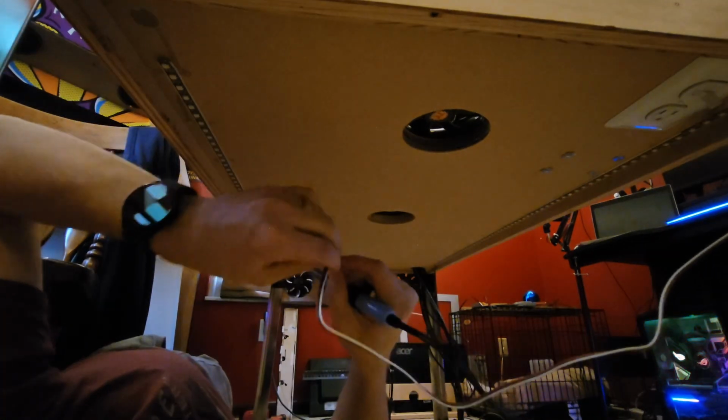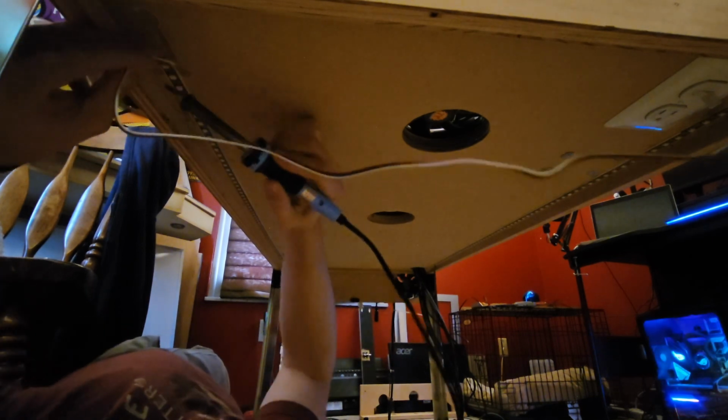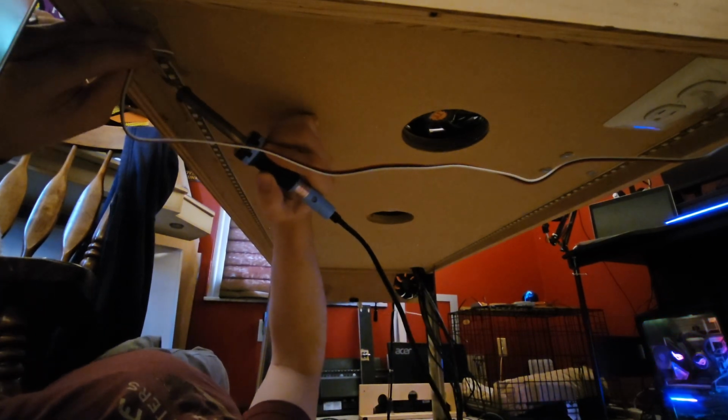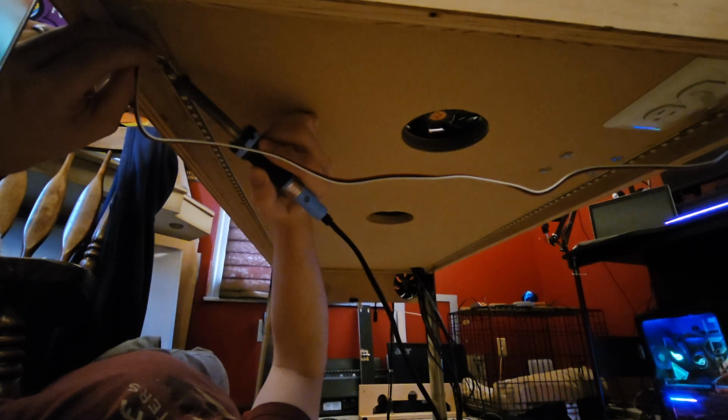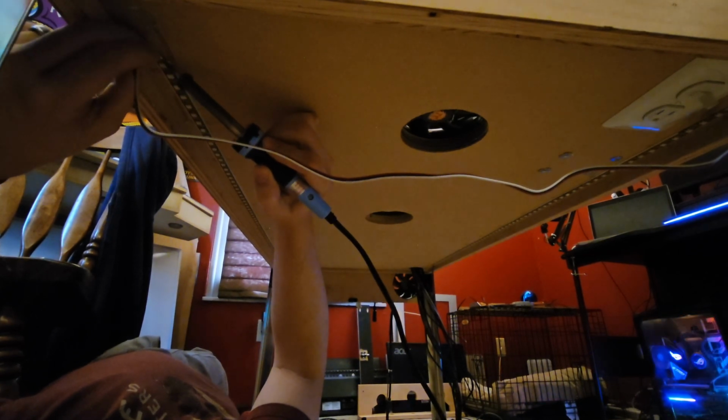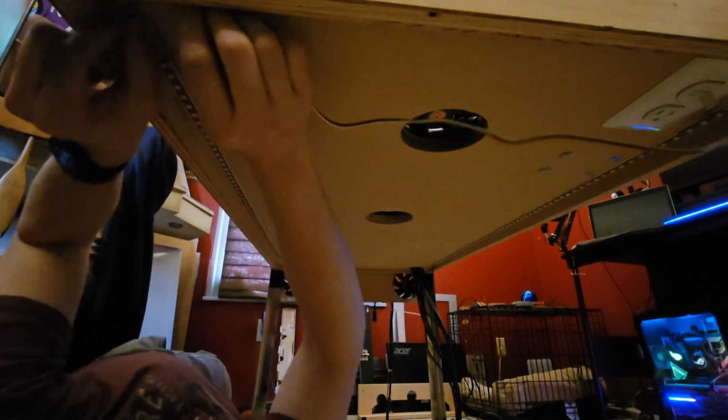As far as power management goes, we're going to inject power at pixel number 1, and we're going to inject power at 124. That's the tail end and the front end. And as I'm soldering these up, you'll see that I tucked the wires back into the holes that I drilled in the back of the cabinet.